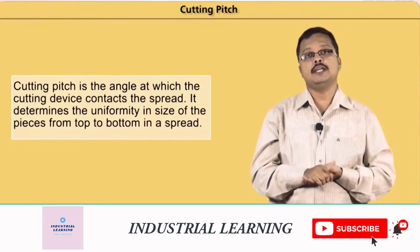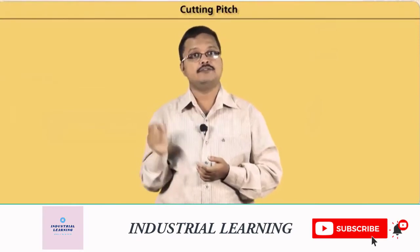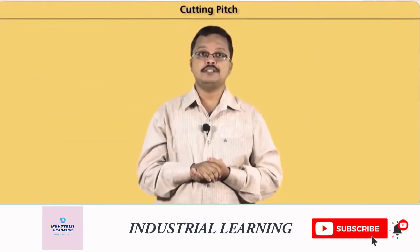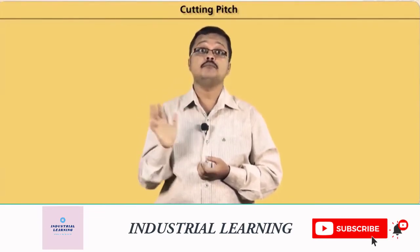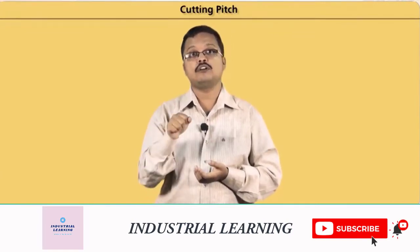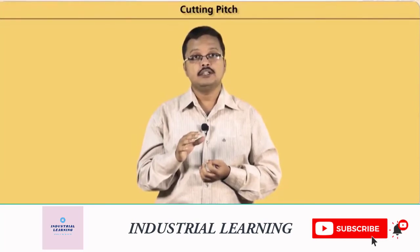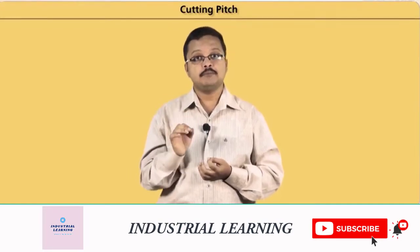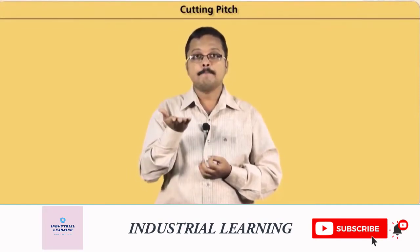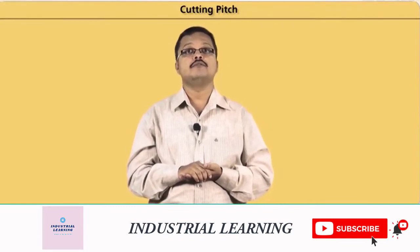In the case of the rotary blade, cutting pitch is less than 90 degrees. The greater the diameter of the knife, the lesser is the cutting pitch, and therefore the top ply will be cut sooner than the bottom ply. If the machine is moved forward at the same time, it will result in uneven cutting. In order to get a uniform cutting through the entire spread, that is vertically, the machine must be kept stationary and the cutter must raise the bottom plies. However, this does not ensure a uniform cut.